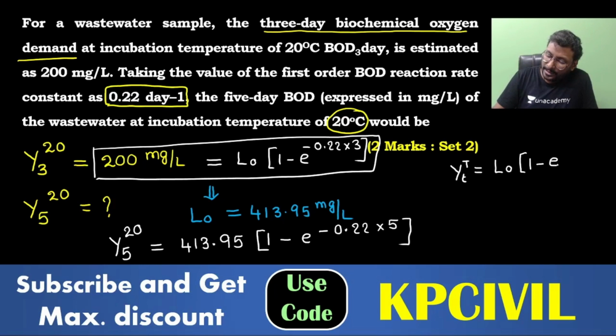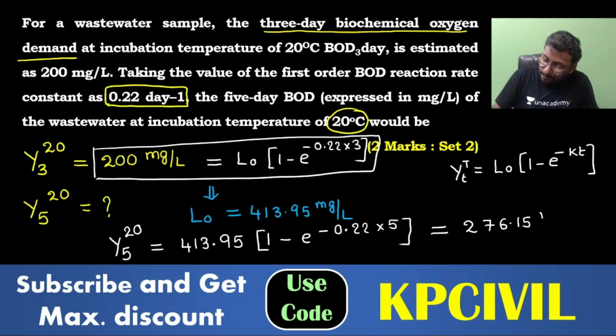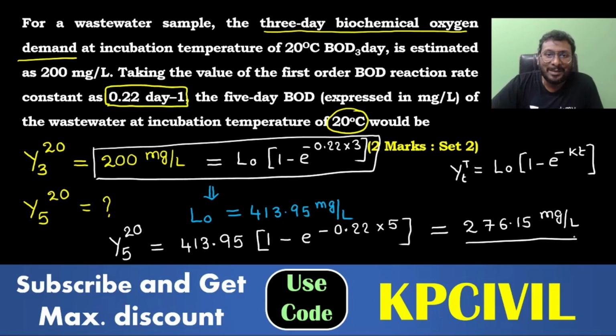Using that, we are getting the 5-day BOD at 20 degrees Celsius, which is 276.15 milligram per liter. Clear? Very simple model. Remember, most of the times GATE will carry a BOD question. Without BOD, mostly we don't have a GATE question paper. Remember that point.